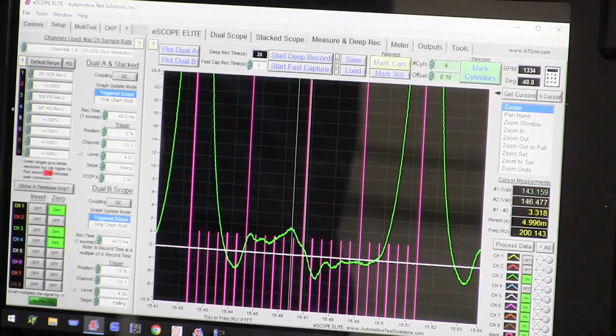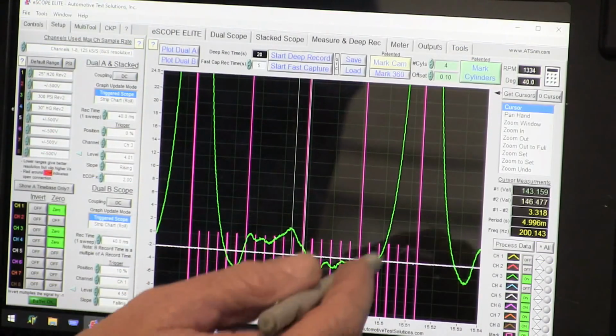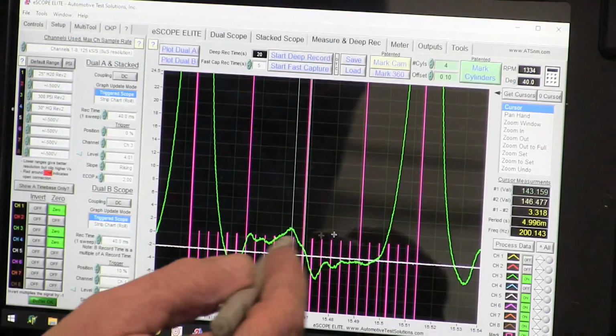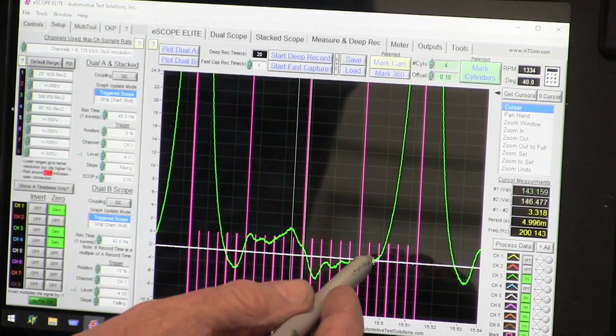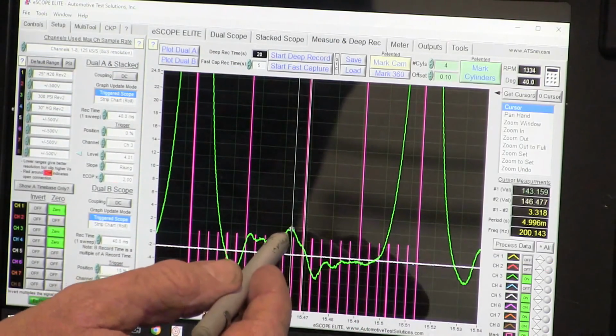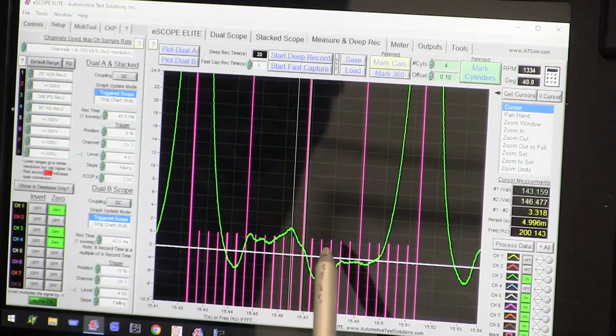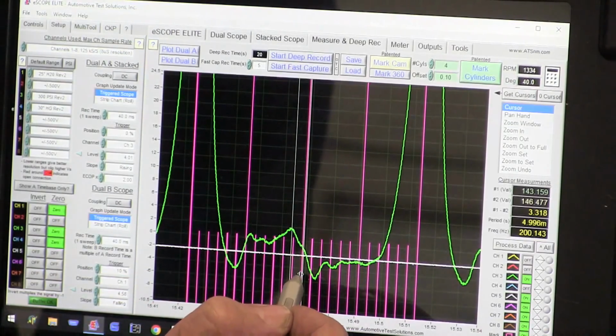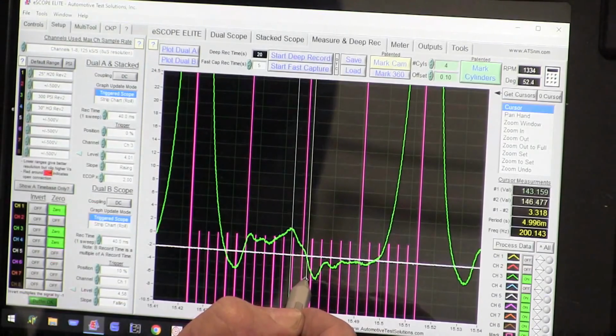Now what I'm worried about is I need to check the phaser and the control of the phaser, but the cam is definitely off. That intake is 40 degrees off on both sides, on this side and this side. So normally this drop is going to happen, that drop on these cars I normally expect to see 10 degrees after top dead center.